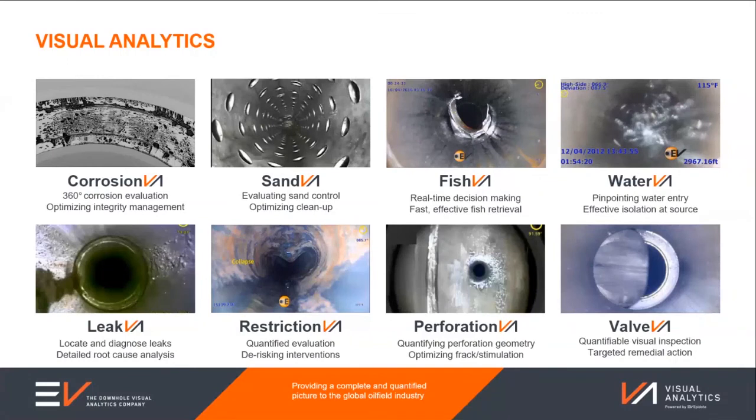Okay, first question first. Centralization. It really depends on the application. For the majority of work we do, yes, we centralize the cameras. Being in the middle of the well gives you the most clear picture. It gives you the widest field of view. And particularly if you're looking sideways at the well, it gives you the best viewing angle to see it from. So most of our work is done running simple centralizers and running in the center of the wellbore.